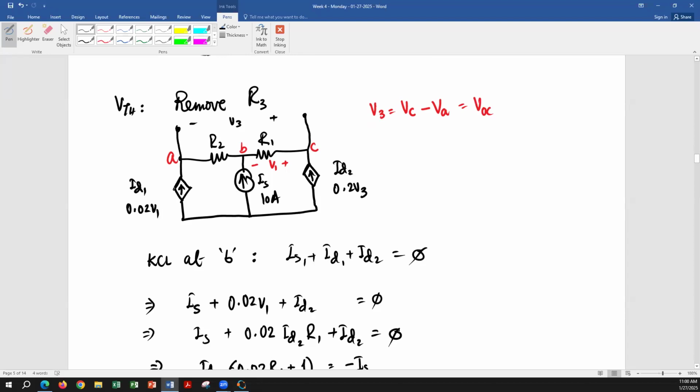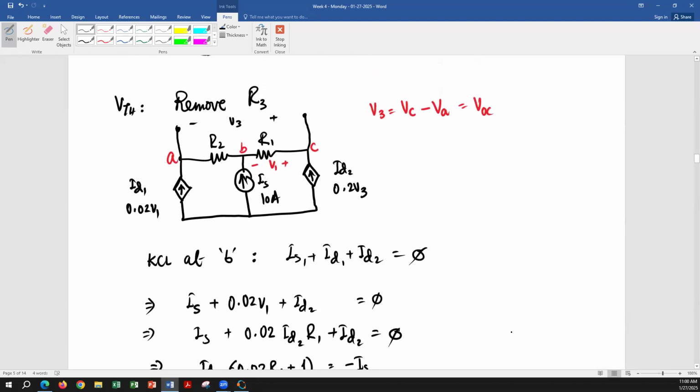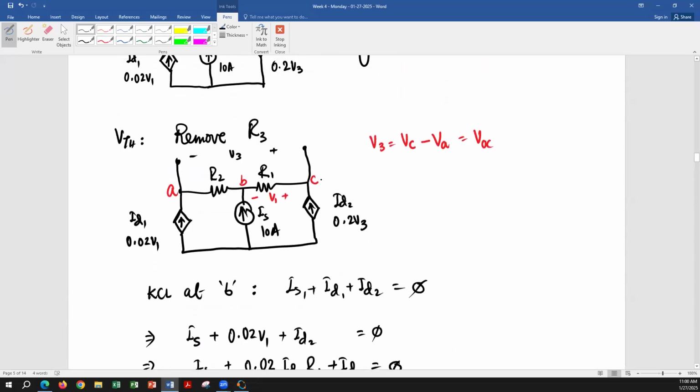These two current sources are going to create a problem because they're in the same loop. Instead of voltage source. Yeah, let's short it. Oh, if we short it, this will be eliminated basically. So you're gonna have R1, R2, short circuit here, and then these two sources here.